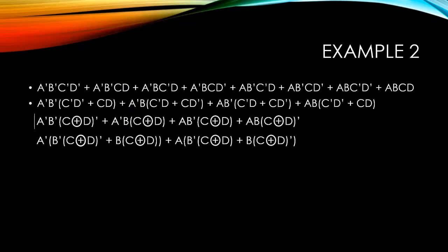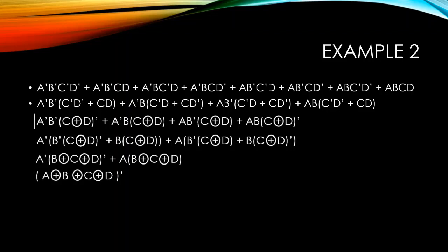And inside the parentheses, we could also say that it could be either XOR and XNOR. So just rewrite it. Okay. So this will be the result. And A naught added to an XNOR, A added to XOR. This is XNOR. Okay. So this will be the result. So from 4 variables for each term, 8 terms in an equation, now we only have 4 variables for each term, okay, and 4 terms only. Okay, so that's how we simplify this equation.